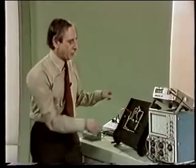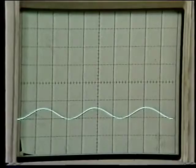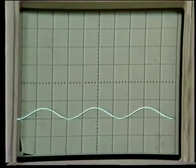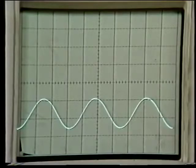I'll close the feedback loop. It's voltage-derived feedback like the first circuit in the unit. Well, the gain is reduced, so I'll increase the input to get back to where we started. Now, the output trace is looking very much more like a sinusoid, so negative feedback has removed the distortion introduced by the amplifier. As we'll be seeing in a moment, negative feedback cannot reduce all types, but the fact that it can reduce some types of distortion is very important in practice. Most amplifying devices are inherently nonlinear, and they can only be used to make linear amplifiers if suitable feedback is applied.